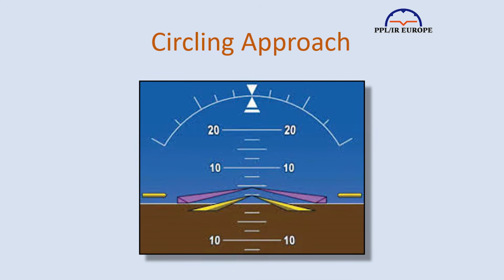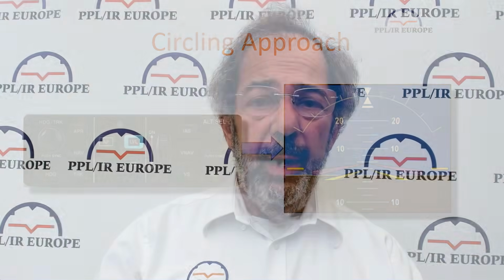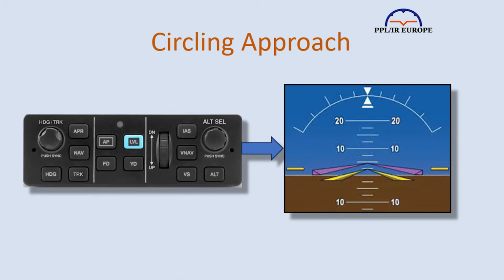However, Flight Director is available. It has the advantage of giving you a single glance to check bank angle and altitude while you focus on visual references, so will help with disorientation. But Flight Director will reflect the settings made on the autopilot, so if you're going to use it, you need to both fly the autopilot and hand fly, which can be an increase in workload and be open to error. You have to ensure that the mode selection is correct.